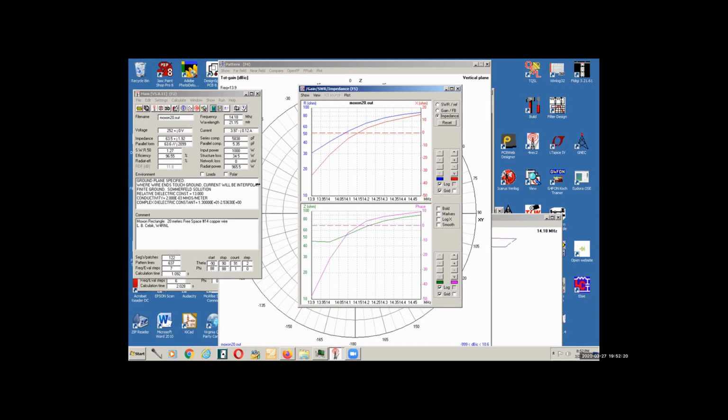I could do that by basically making a wire grid. Again, same criteria: the area of that grid's got to be less than 1/100th of a wavelength. But I would just model that. I could actually model the flat measuring tape, because now we're talking about not a round wire, but a flat element. So yeah, the code can definitely do that.